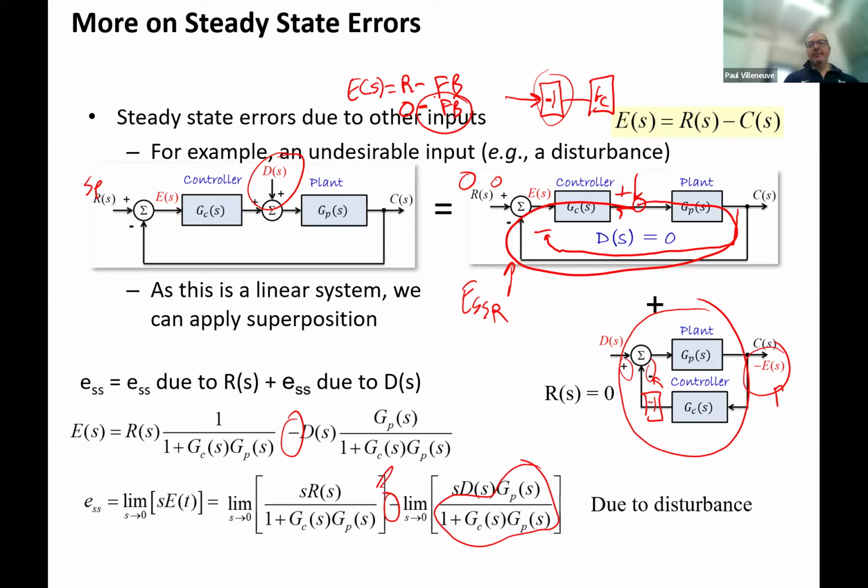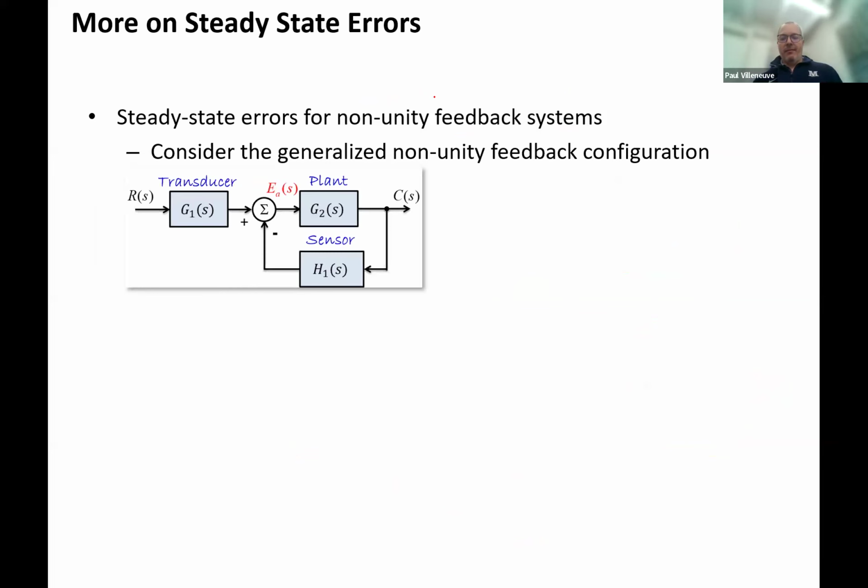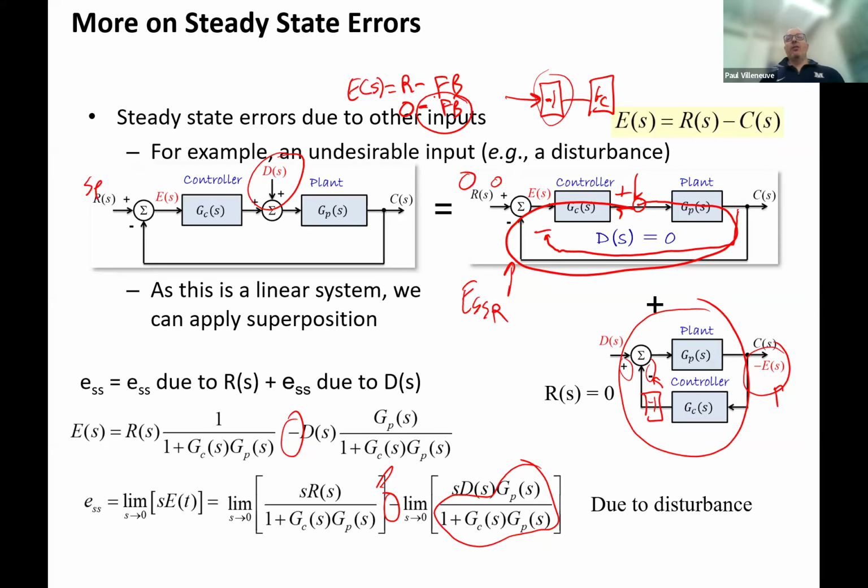Okay. So that's the only thing that you have to add on it. Just have to add on the disturbance signal. And most of the time, because you don't know what a disturbance is, you've just got to take a guess. So is it going to be a step input or ramp input? You don't know. It all depends on the process. So somehow you have to become a master at being able to do that.